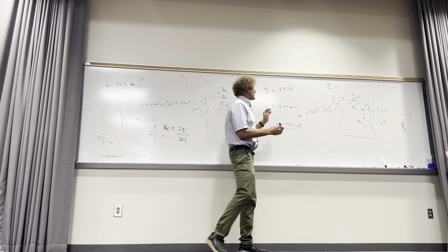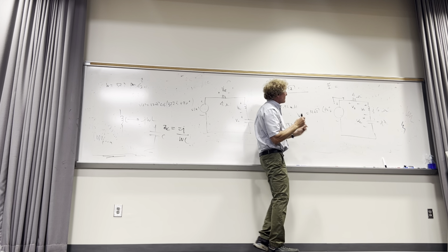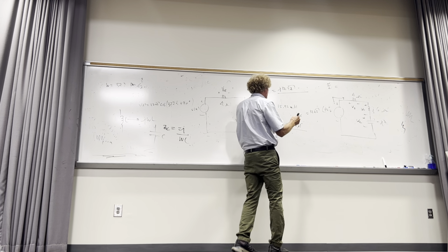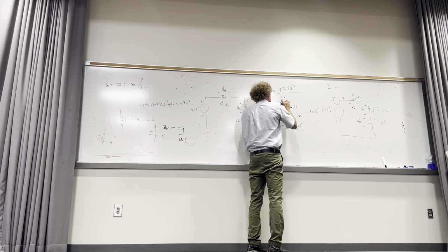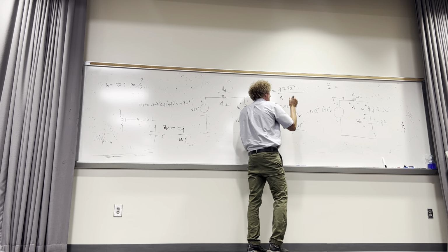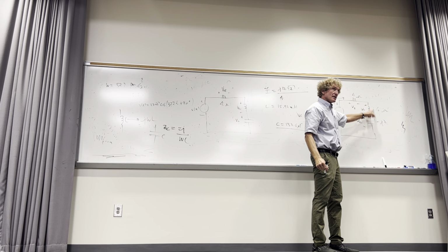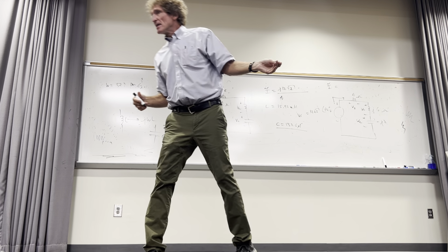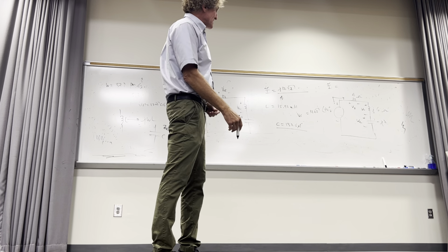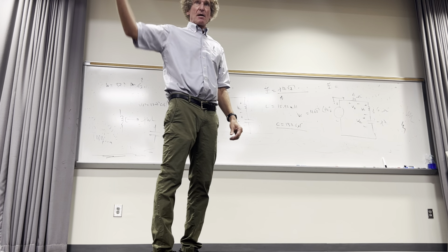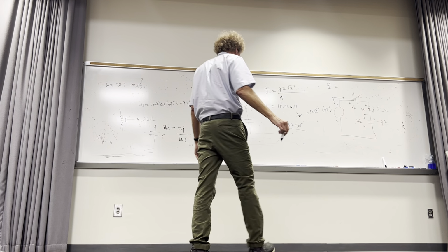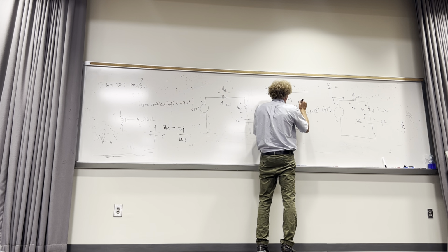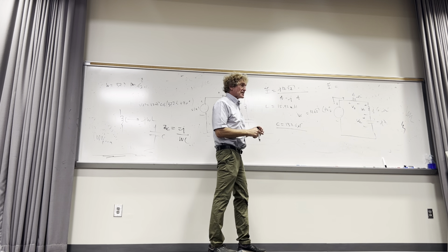Now you divide it by everything. Obviously, we got 4 ohms, right? That's the first thing, but what about the second thing? I'll just put 4 here. What about this? What can we do with these two? It results in J4, right? J6 minus J2 is J4. How many see that? Good. So I got 4 minus J4. Now I'm going to tell you this right now. That would be the current.